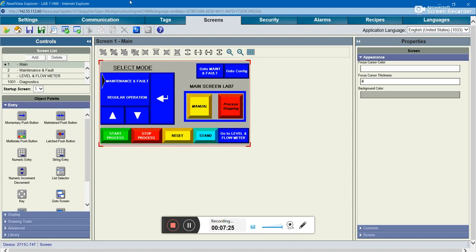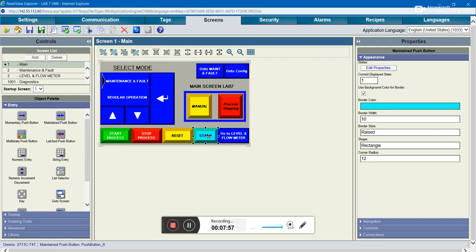So once you start, the main thing is to connect with the HMI, which you need to program the user interface for. Then second is the PLC you are assigning tags or buttons or any indicators for. For the tags, all the inputs and reading values, addresses should be mentioned in the tags. The screen is just a user interface you make, and once you're done making the layout, you just assign the addresses and you're good. So yeah, that's it.